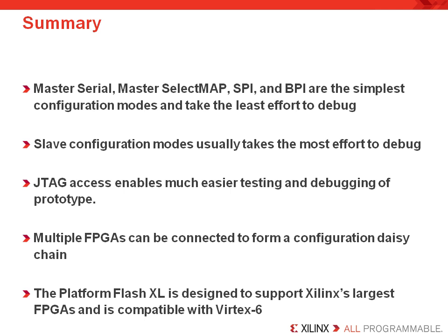It is always a good idea to support a JTAG configuration scheme when building your system in case you need to debug your design later. Multiple FPGAs can be connected to form a configuration daisy chain. This allows designers to program multiple FPGAs from a single flash component.